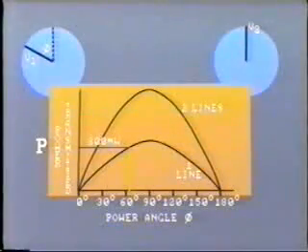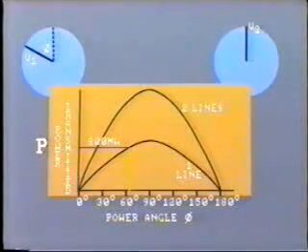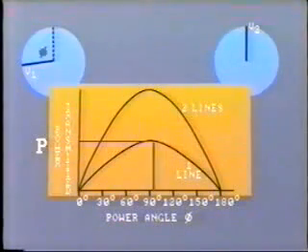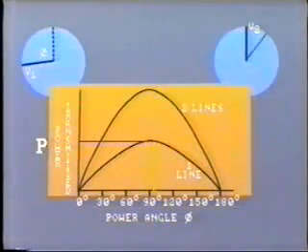Now, in this precarious situation, any disturbance on the power system, say a loss of load or a loss of power generation, may cause the voltage at V1 to advance further, or perhaps the voltage at V2 to lag such that the load angle between them exceeds 90 degrees.